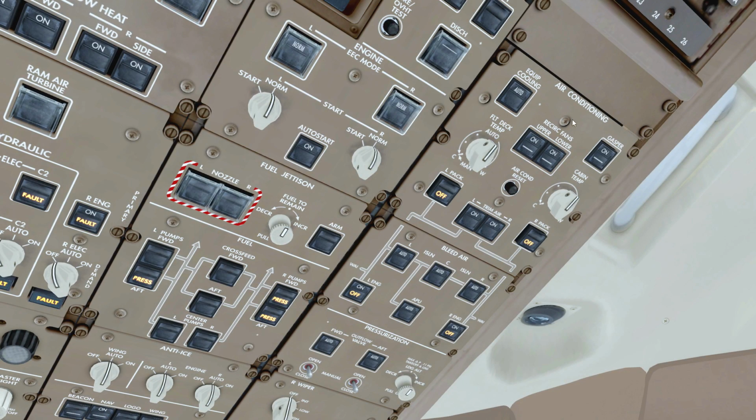Then the last column, air conditioning panel, pretty much speaks for itself. You want to have the equipment cooling on auto, just leave it as it is. The rear circulation fans, basically circulating air in the cabin, you just want to have them on. The gasper is on, those little air vents above your head in your seat, which you can turn on yourself. That's also on for the comfort of the passengers.